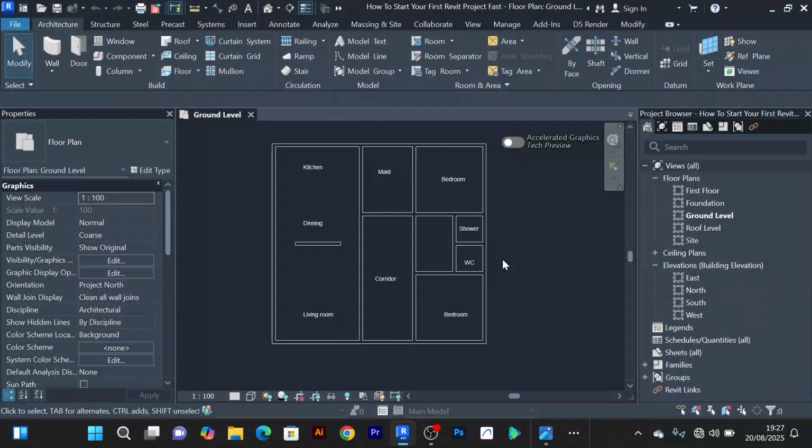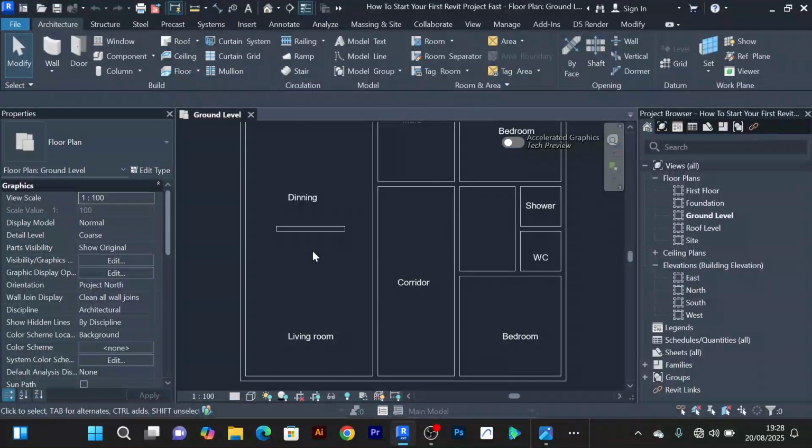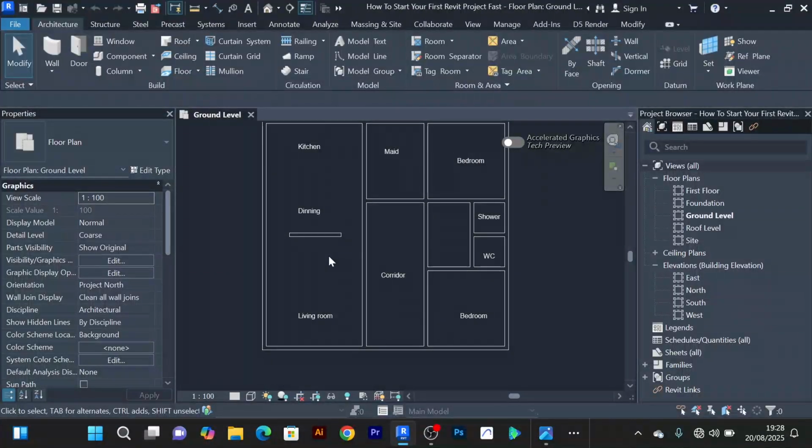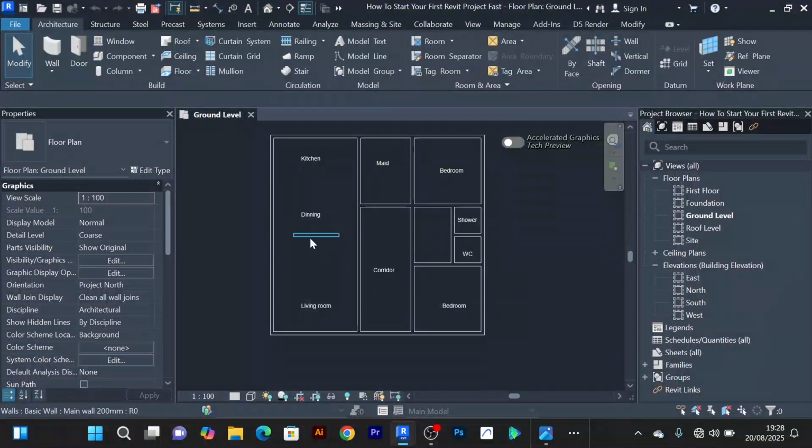Now today we're going to focus on the first floor. We should be able to finish the first floor, and we see how far we can go with that. But of course, going straight to the project, we need first of all to create a stair here to take us to the next level. So now, to create a stair, you just go to this architecture, then you look for stair.